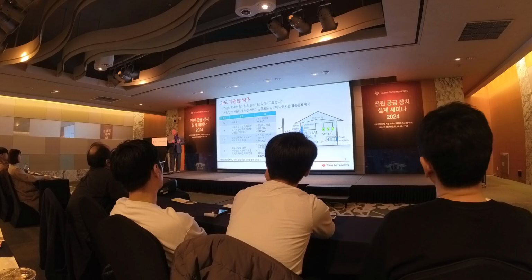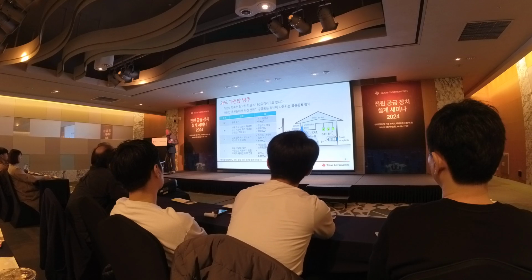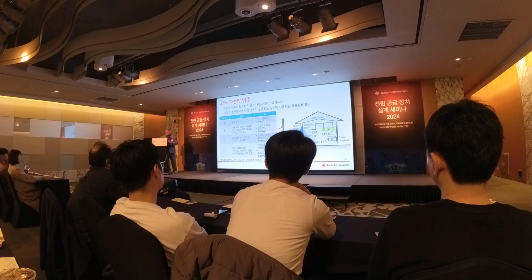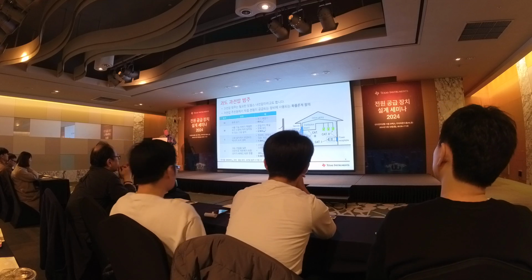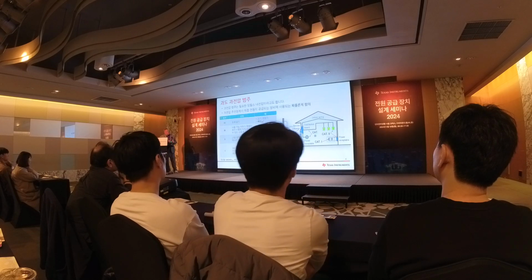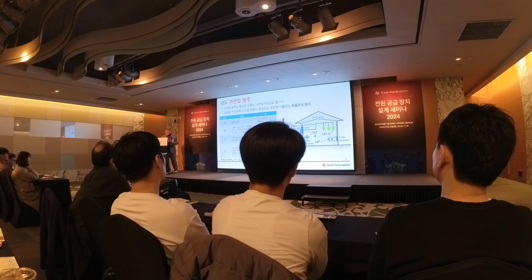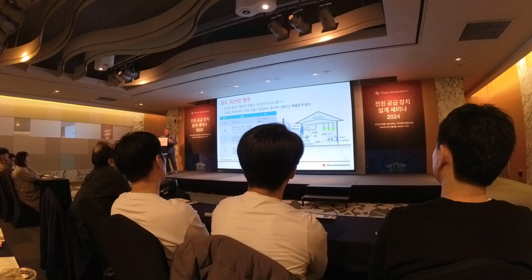Those are category 4. And these need to typically have up to 4 kV peak transient overvoltages. Now, category 3 is then the fixed installation where the availability is subject to special requirements. So this is once we have the service coming into your house, this is the service panel. These are outlets that are connected directly to that distribution panel.